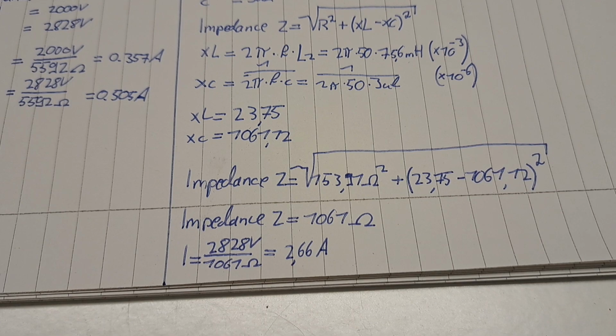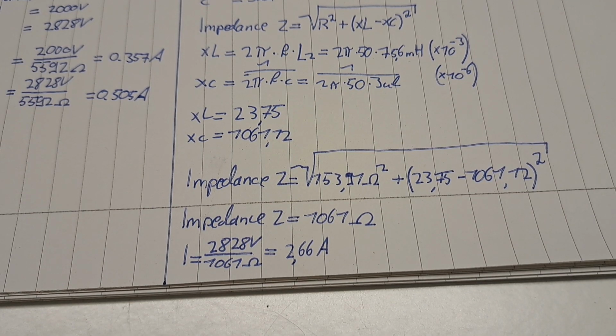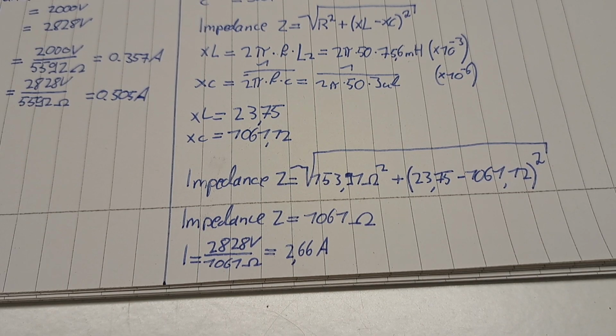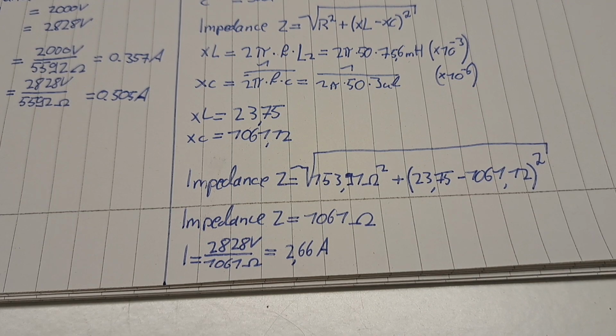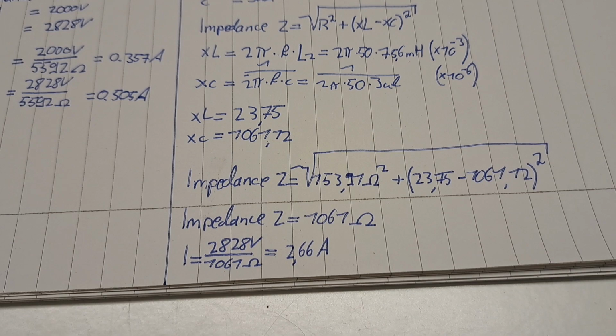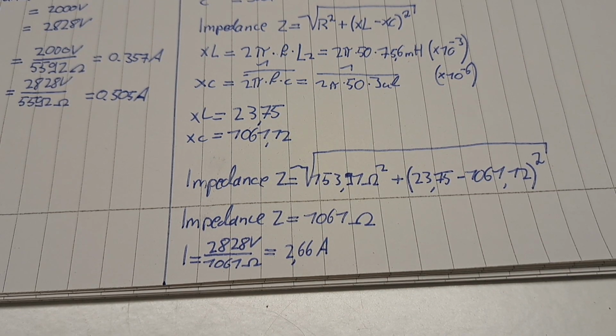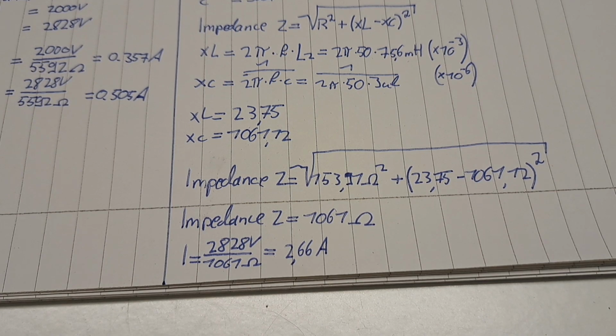Now we could theoretically increase the capacitance even more to get even higher currents. With 5 capacitors or 5 microfarads, we get a way higher current, around 5 amps, but that would be way too much for the secondary side and also for the primary side, because it would be way over the 3600 watt limit that a normal 230 volt circuit can deliver.